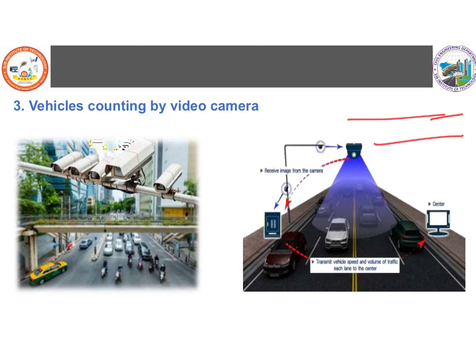Identify one elevated place, so that you can see the movement of vehicles. At such an elevated place, fix up one video camera, switch it on and leave it. That will record the passage of each and every vehicle. Then go back to your office, play that video, and note down the number of vehicles passing that particular point in a given interval of time.